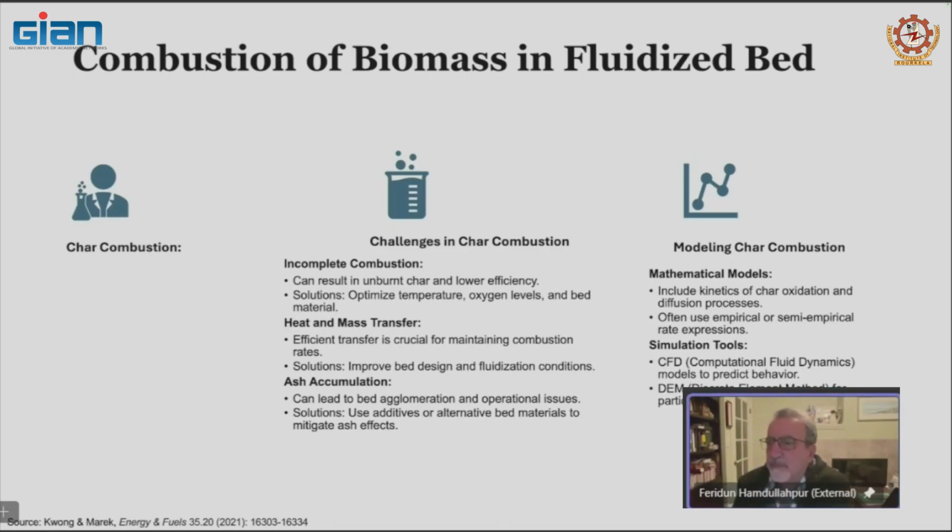Very good question. Both options are possible. In some cases, we use the fluidized bed as a combustor, but everything I say is steady state. When you start from cold, it's a different operation. You will need a secondary fuel like propane, natural gas or liquid to bring the bed to the operation temperature, at which point you can start feeding the fuel.